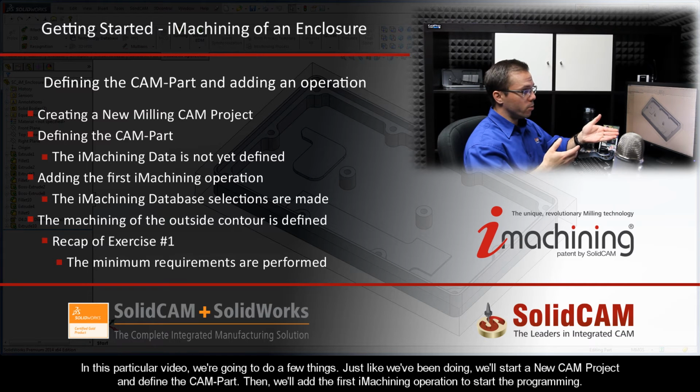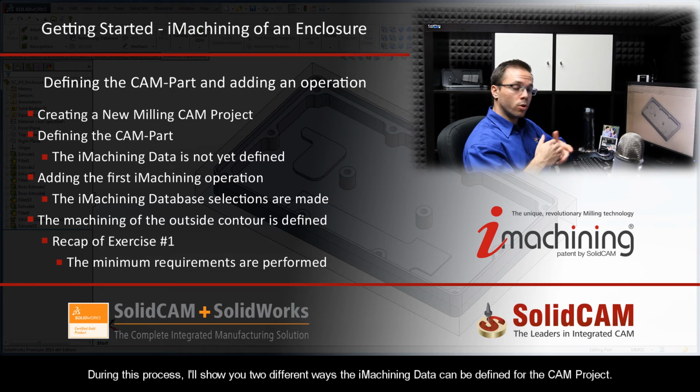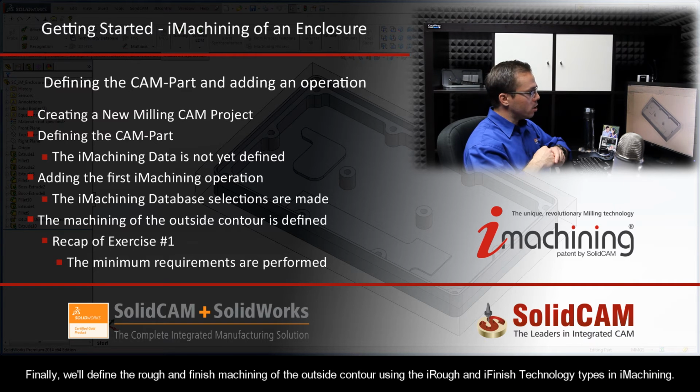In this particular video, we're going to do a few things. Just like we've been doing, we'll start a new CAM project and define the CAMPart. Then we'll add the first iMachining operation to start the programming. During this process, I'll show you two different ways that the iMachining data can be defined for the CAM project. And finally, we'll define the rough and finish machining of the outside contour using the iRough and iFinish technology types in iMachining.